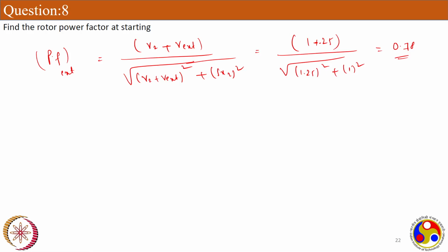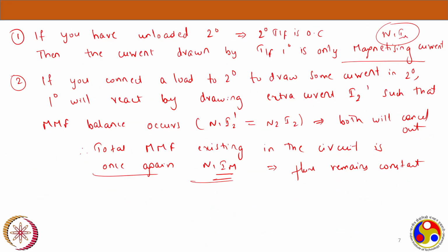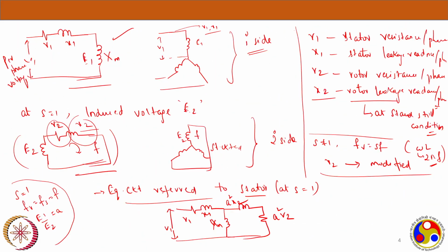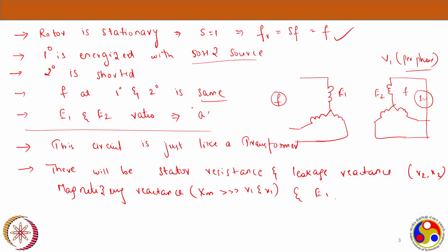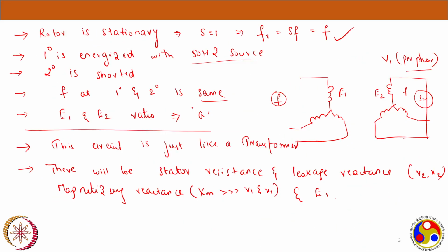The main focus of today's discussion is on the equivalent circuit of the induction machine. We arrived at the induction machine with the concept of the transformer. Now, efficiency decreases, losses will definitely be more. That's why we remove the resistance as we run the motor. It's not advisable to add an external resistance, except at starting to get a good torque and also improve power factor.